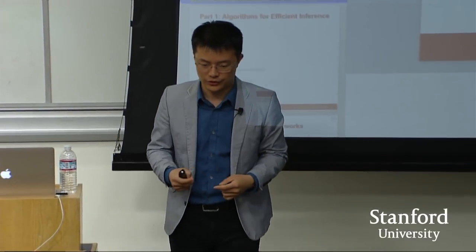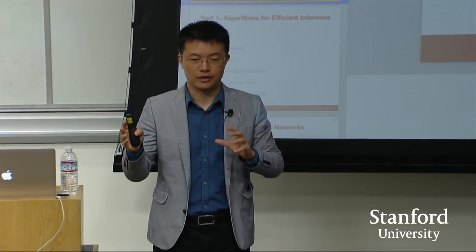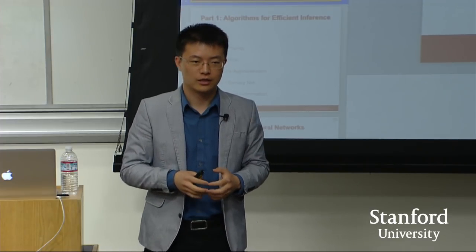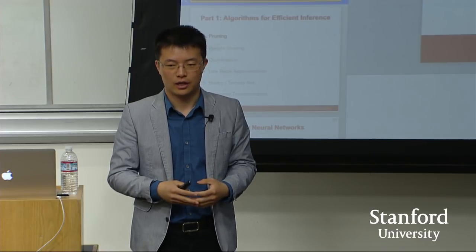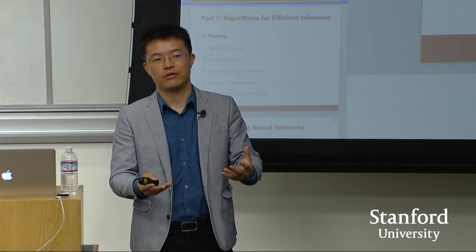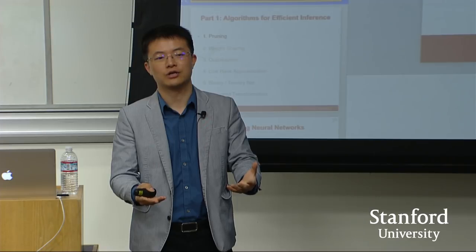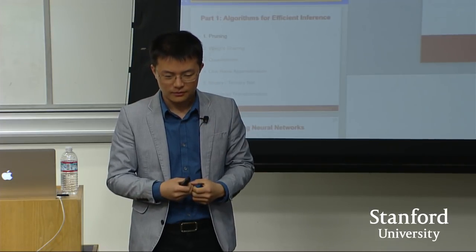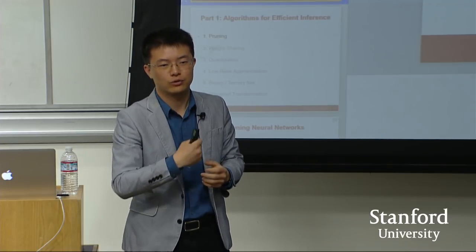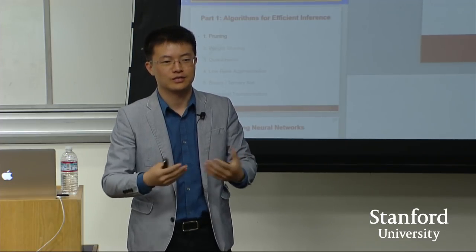Yeah, so the trade-off is always power, area, and performance. In general, all the hardware design has to take into account the performance, the power, and also the area. When machine learning comes, there's a fourth figure of merit, which is the accuracy. And there is a fifth one, which is programmability. So how general is your hardware?